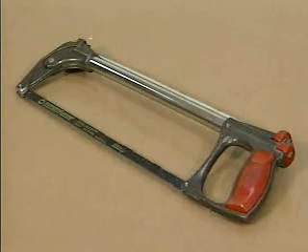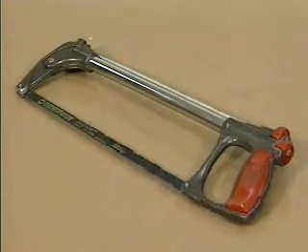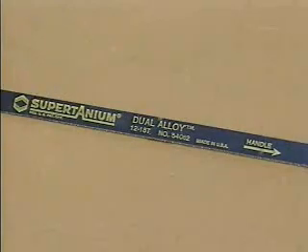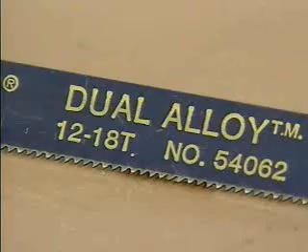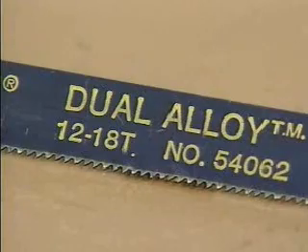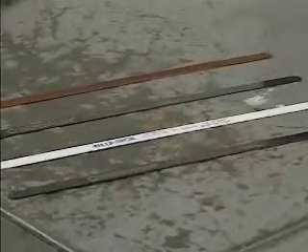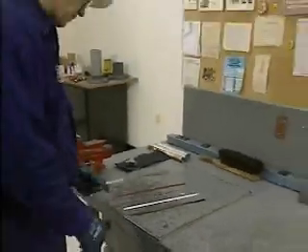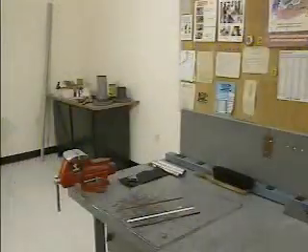In addition to pipe cutters, hacksaws and bandsaws are commonly used to cut metal and plastic pipe. We'll look at both of these tools, beginning with the hacksaw. Hacksaws have hardened tempered steel blades. A pitch of 1/18, for example, means that the blade has 18 teeth per inch. The most common blades used for cutting pipe have 14, 18, 24, or 32 teeth per inch. Thin-walled pipe generally requires a blade with smaller teeth or a higher pitch. Be sure to select the blade with the correct manufacturer-recommended pitch for the pipe you are cutting.